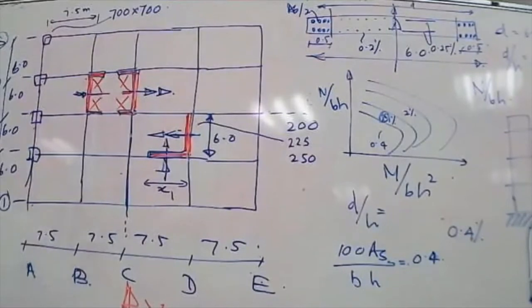Yes, sir. In a wall, you have designed it as a column. So in a column, we do restraining of alternate bars which are 150 millimeters away from a restrained vertical bar. Do we apply that same concept for this wall reinforcement?